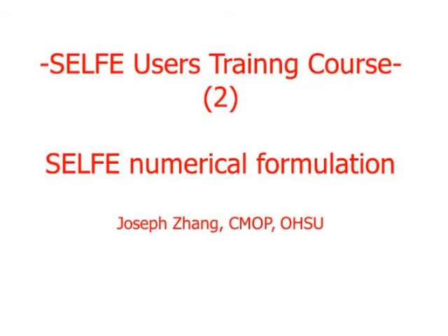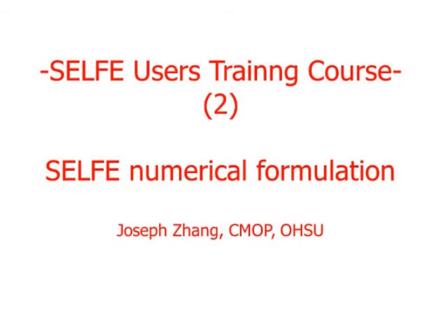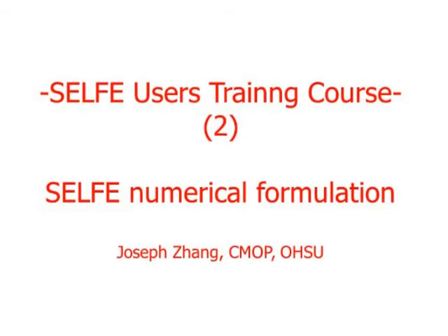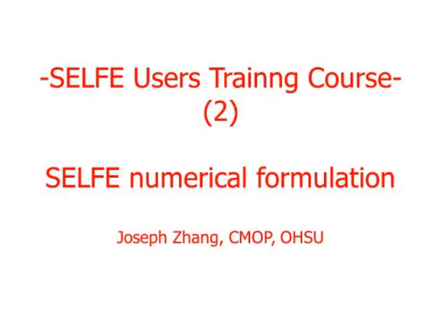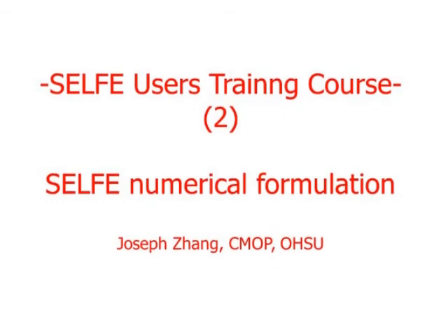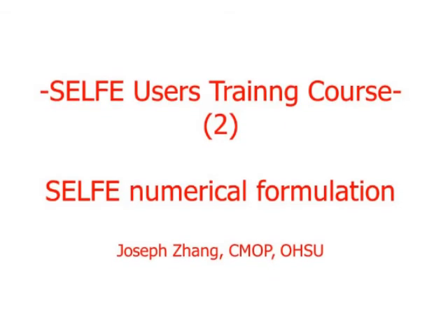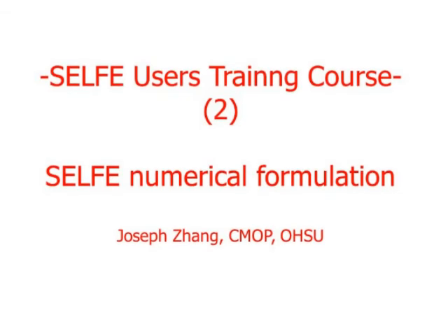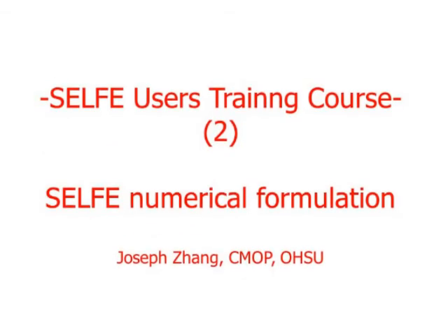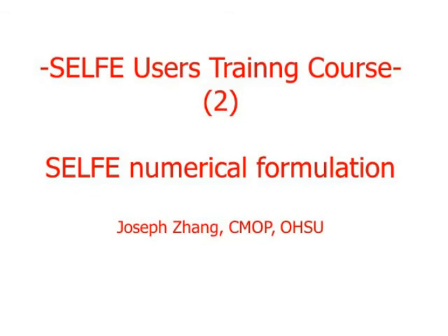They basically treat this term either implicitly or explicitly, depending on its sign. If it's negative, you treat it implicitly. The reason is actually very simple: if the whole thing is negative and you put it back on the left-hand side, it becomes positive. So you are enhancing the diagonal, making it more stable. I think that's the reason they do these kinds of tricks.